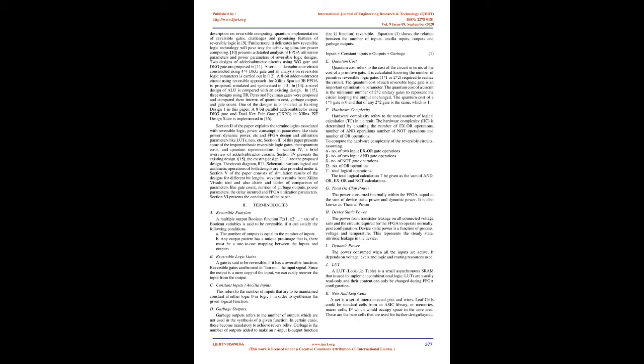These designs are analyzed and simulated using the Xilinx Vivado tool and implemented on the Zedboard Zynq 7000 Evaluation and Development Kit, XC7Z020CLG484-1. The proposed design outperforms the existing designs. Keywords: reversible ALU design, reversible logic, reversible adder/subtractor, low-power VLSI design, high-speed adder.